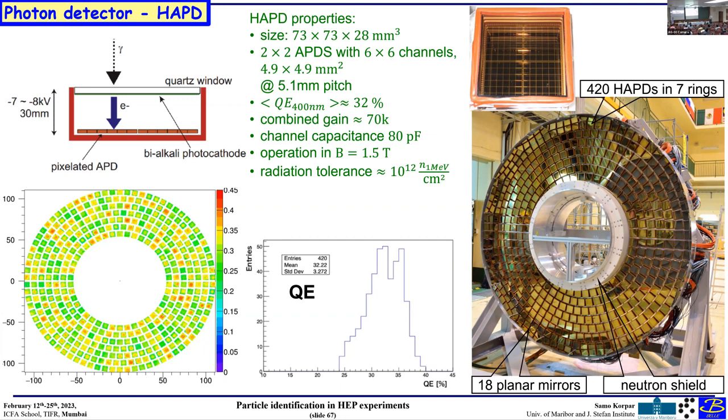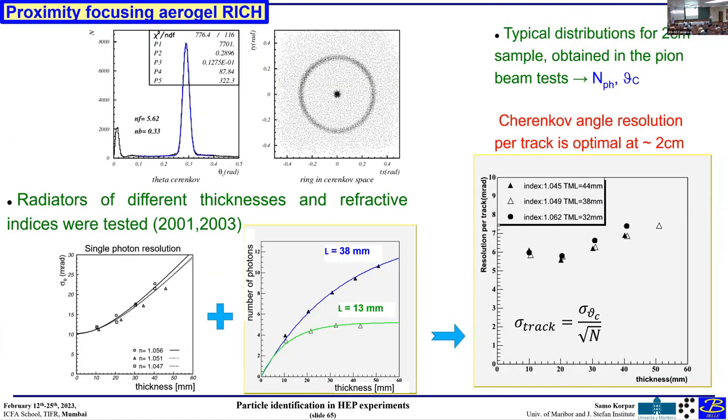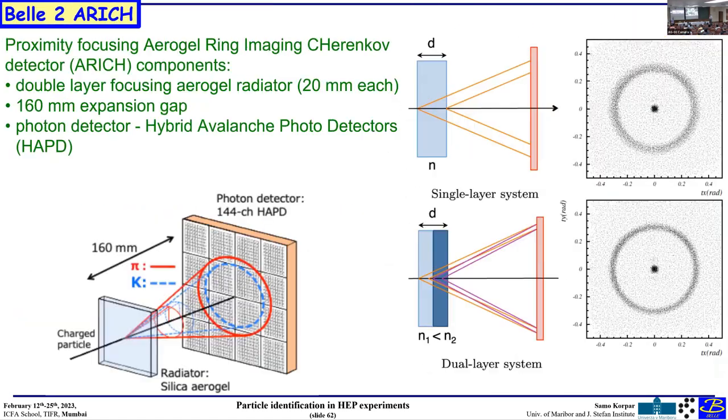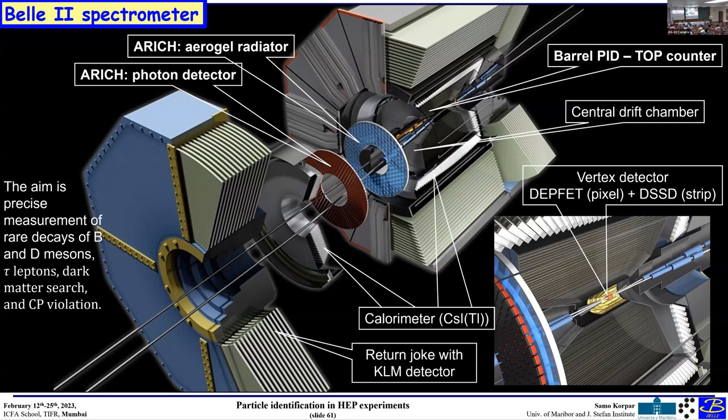And the standard PMTs actually do not work in strong magnetic field because the size of the dynode structure is too large. If I go to this, okay. So basically, the normal PMT already has problems at 0.1 millitesla. In the multi-anode PMTs, about 15 millitesla has a problem. MCP PMTs can operate up to 2 Tesla or even more, depending on the structure.